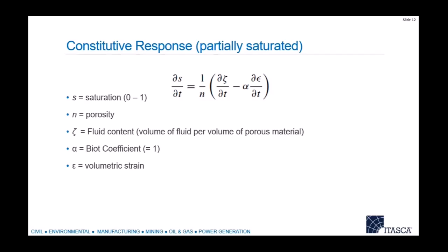In this case, the fluid content is just the amount of fluid available in that pore, which is the total amount of volume represented by that pore system, right? 0, there's no water. 1, it's completely full, but there's no pressure yet. And all this is saying is that saturation drops as the fluid water content drops, and again, as you squeeze it through this Biot coefficient, which by default is 1.